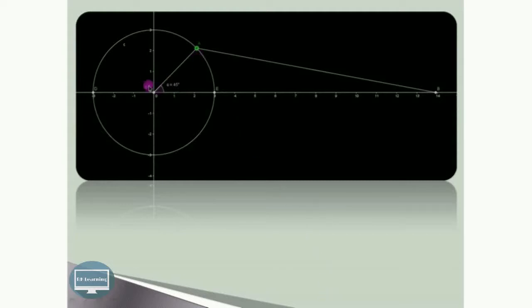Now this OA is the crank which is rotating uniformly in anti-clockwise direction as we have seen in the earlier animation. AB is the connecting rod and it is oscillating, and the oscillation is non-uniform, and B is the piston which is sliding inside the cylinder in reciprocating fashion, so it will have linear acceleration. Now as this particular crank is rotating uniformly, it will have only radial acceleration or centripetal acceleration.